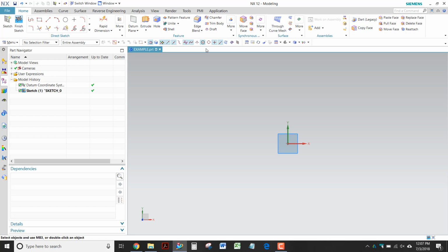So here we're going to be able to show some simple shapes we can make. So we're going to actually start with lines and arcs. So if you want to make a simple line, you can select line here. You can select specific parameters if you know your exact dimensions of the line you want, or you can go X, Y, and place your line wherever you'd like. So you go first click. You don't have to click and drag, you just do first click and second click,